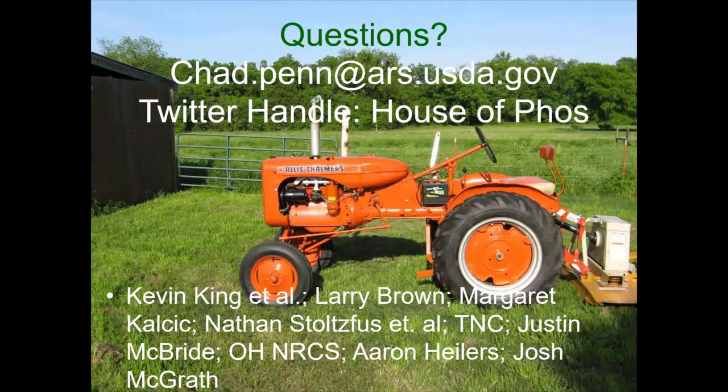We've got much better best management practices for reducing sediment and particulate losses. It will filter out particulate P, but it's kind of an expensive way to do it. So, the short answer is you should only be doing this on sites where you've got erosion under control already, and the soils are built up very high in legacy P. So you just got to keep sediment out of it through other means. It'll remove it, but at what cost?